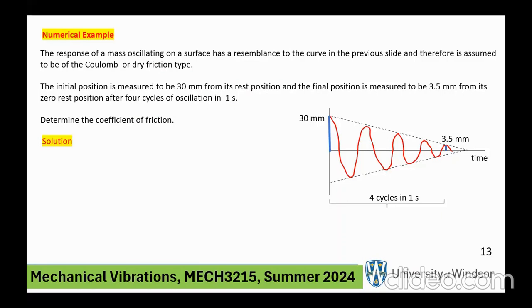And the most reasonable thing to do, at least deciding between viscous damping and Coulomb damping, this is a contact problem, so Coulomb damping is more appropriate. And let's say that we measure the displacement of the block as a function of time, and we notice that actually it looks like this. Notice that the amplitude of the block is decaying in a more or less linear fashion. Therefore, that's another indication that Coulomb damping is more appropriate.